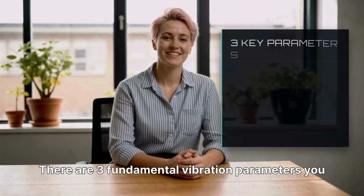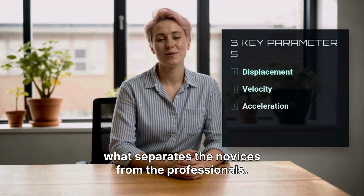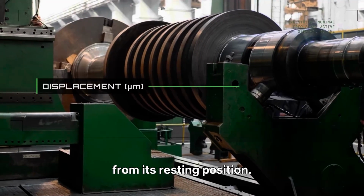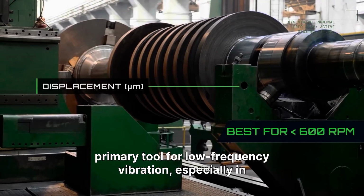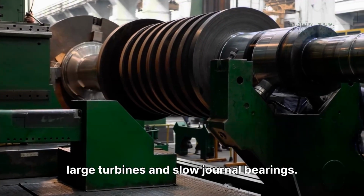There are three fundamental vibration parameters you must master: displacement, velocity, and acceleration. Knowing which one to focus on is what separates the novices from the professionals. Displacement measures how far the machine moves from its resting position. It's measured in micrometers and is your primary tool for low-frequency vibration, especially in large turbines and slow journal bearings.